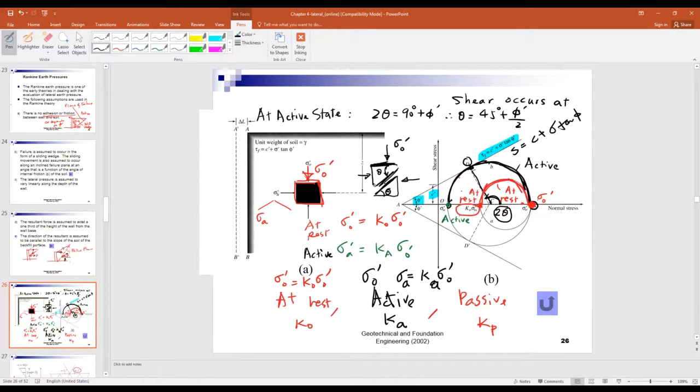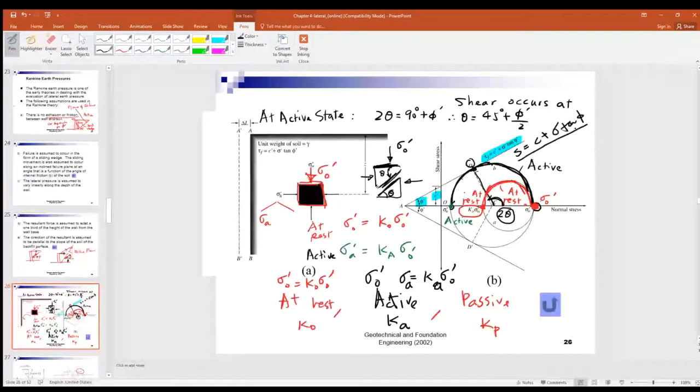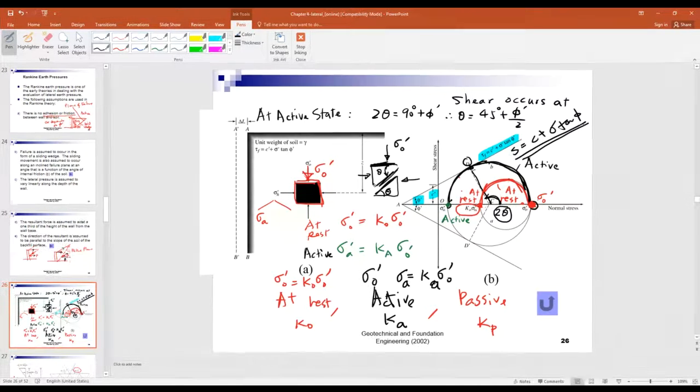Whenever the Mohr circle touches that shear strength envelope, it will fail, because the soil cannot exceed that strength. So whenever the Mohr circle touches or even passes through or cuts across it, that's impossible. The soil will fail first, right? So that is the limiting stress that the failure plane could take.